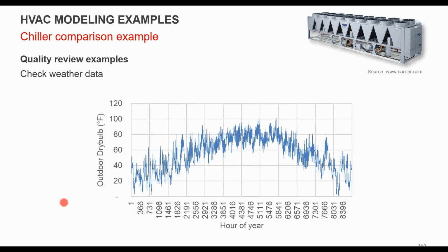Make sure that you selected the correct weather file for your location. And if you have actual year, more recent weather data, that usually is a better indicator of actual performance. So this is a TMY set for St. Louis, and that's a good starting point. But I would imagine if you grab current year weather data, you're going to be substantially higher in the summer up here when you actually look at your peaks. TMY tends to be a little bit more smoothed out.